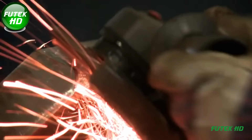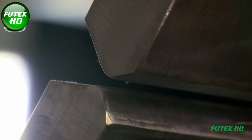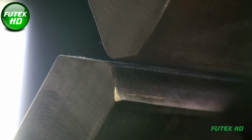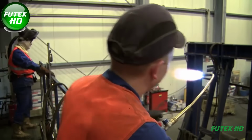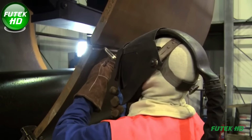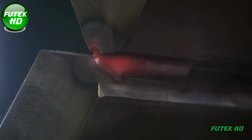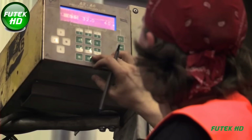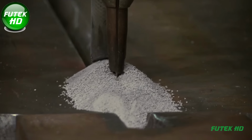The edges of the plates are precisely prepared for welding. Before the plates are joined, the metal is heated to the required temperature, which prevents cracking during the welding process. A welding robot creates the final weld seam, a task that takes up to 16 hours per pipe. Throughout this time, the weld must remain at a consistent temperature to avoid any weaknesses in the joint.